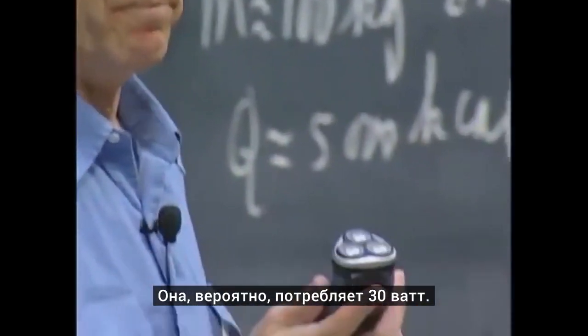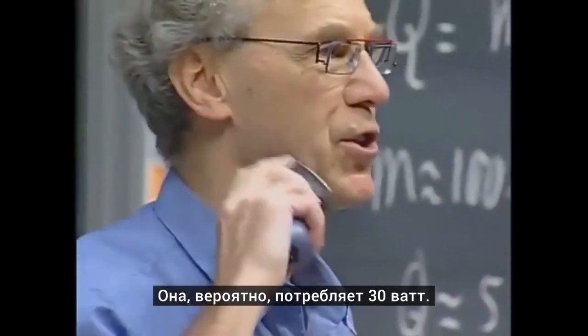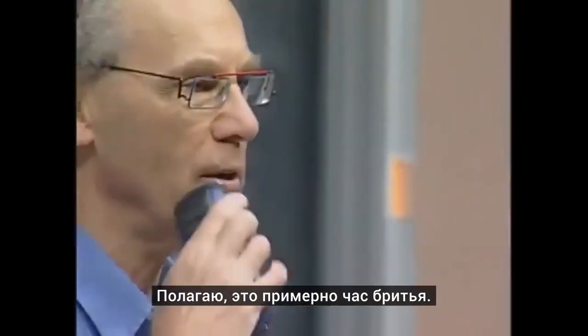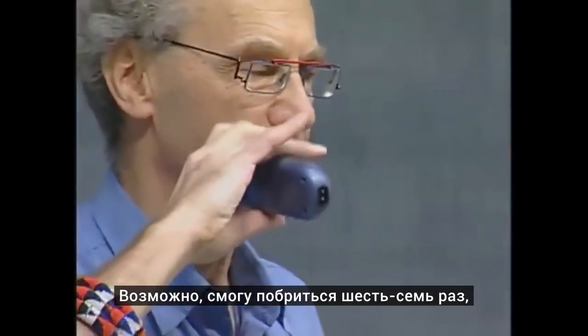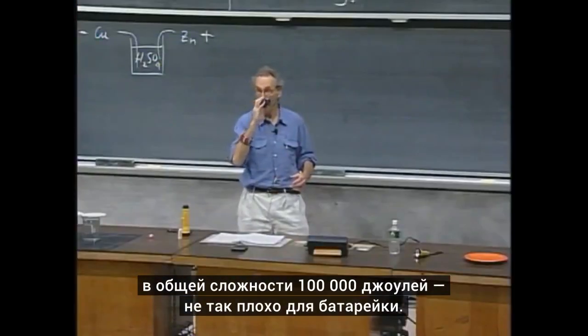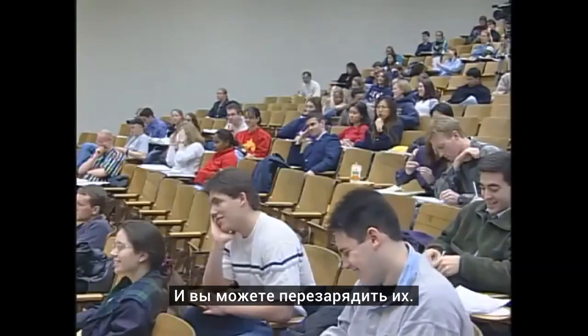This probably consumes 30 watts, 30 joules per second is my rough guess. And I can probably get 1 hour of shaving out of that. Probably shave 6, 7 times. So that's a total of 100,000 joules. It's not bad out of a battery, and you can even recharge it.